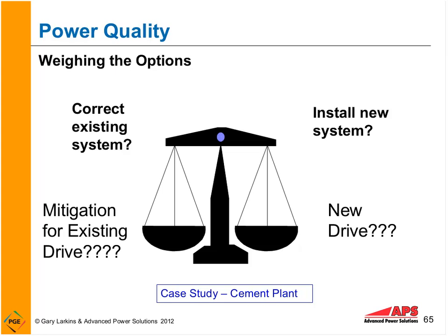They wanted to know, do we have to install $1 million more worth of mitigation equipment? And looking at the installation, there was newer drive technology that was a lot more tolerant. It was more efficient, more tolerant. So rather than spend $1 million on adding to what you would call mitigation equipment, or equipment that could make those drives operate, the simple solution here is go in, get a rebate, replace your existing drives, make sure the new drives are specified properly, and install those and test them and verify that they work properly.